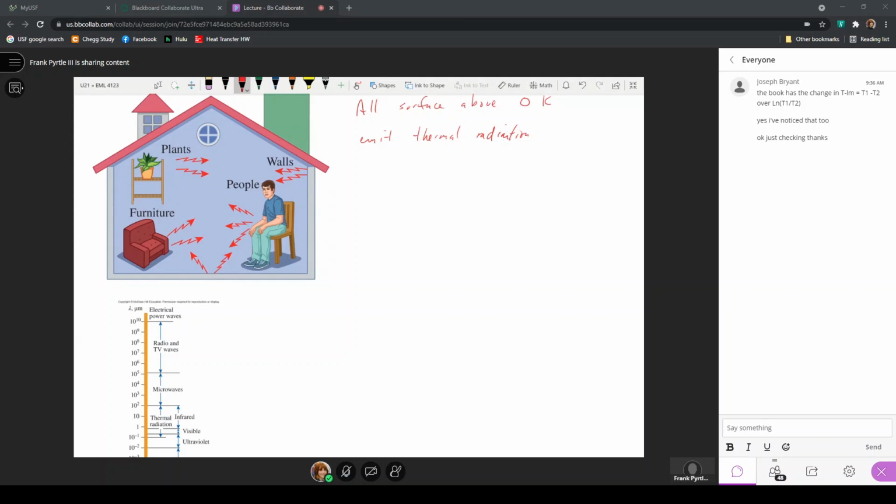This is also the reason why when you walk past a cold window in the wintertime, if you're walking down a hallway that has windows not covered by drapes, you may feel the hairs on your arms stand up. That's because of the heat flux by radiation. If there's a window that is exposed to cold air, the glass would be much closer to the cold temperature outdoors than the interior drywall.